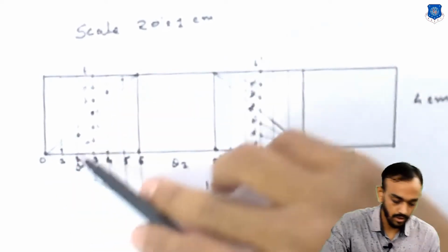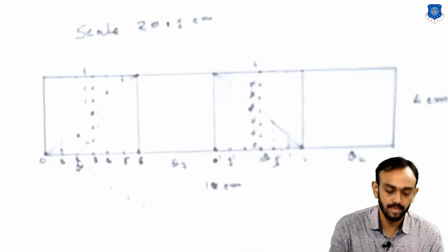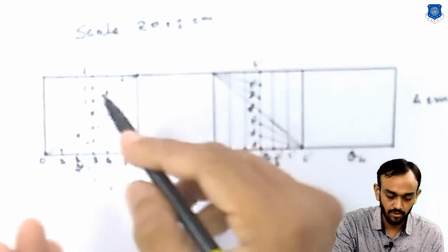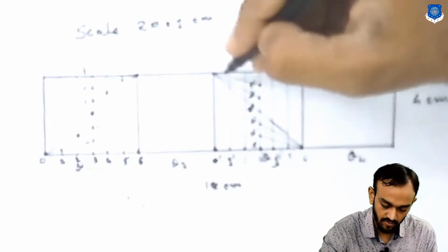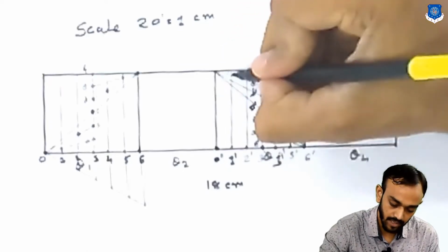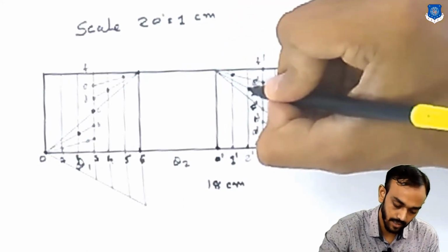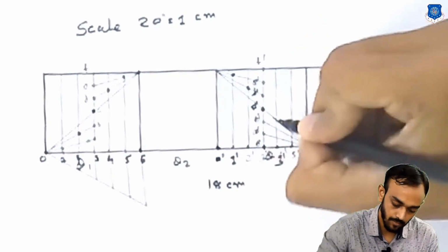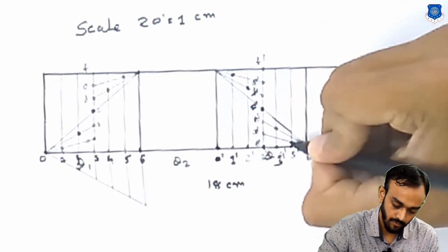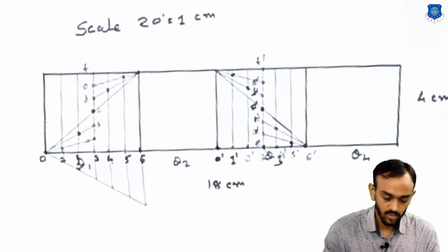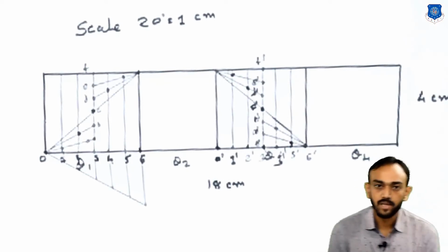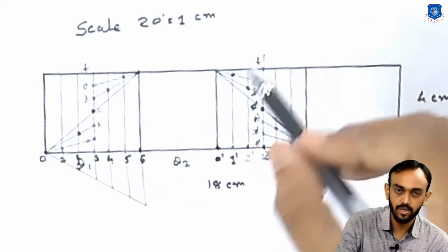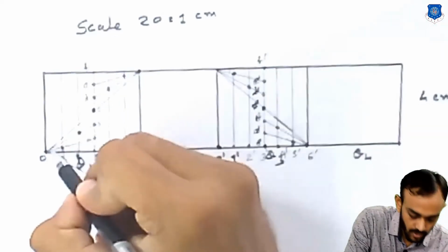And when you draw the line from these points, you will get the uniform acceleration for the rise, and same you can see this is our first inclined line and our vertical line, this is the intersection point here, this is the third point, fourth, 5, this is the end. So now you have to draw this curve here very gracefully.